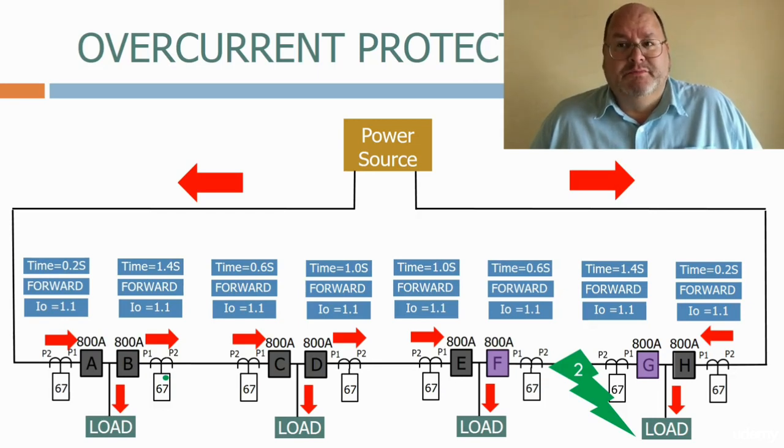This delay may be acceptable for some distribution networks, but if we try to hold off for this long on a transmission network, the high level of fault current would critically damage the equipment and probably cause a system-wide collapse. In the future Advanced Protection System course, we will look at some different types of protection that combine an ability to provide good fault discrimination, but do it in a reduced clearance time.